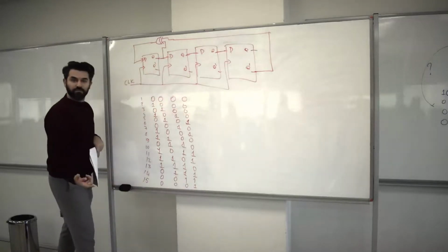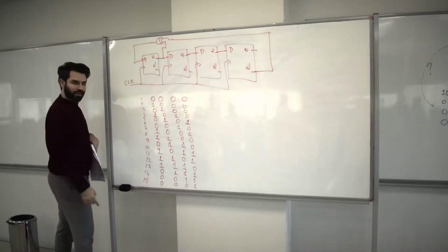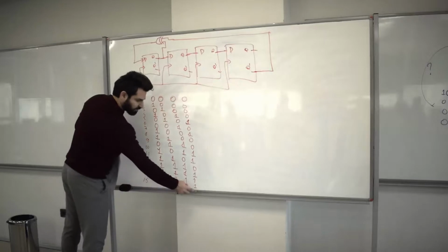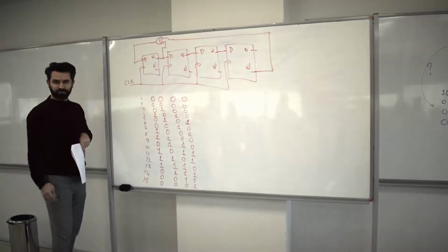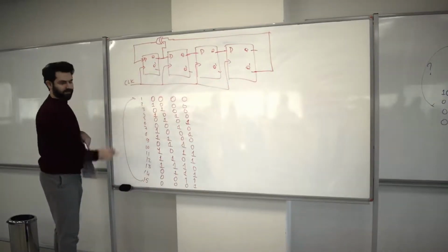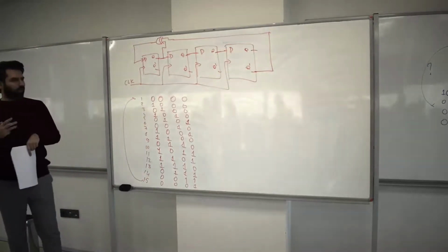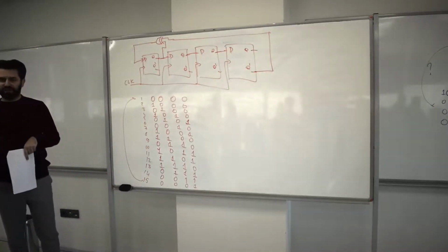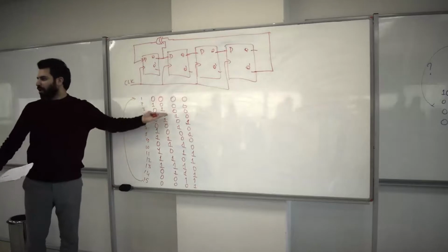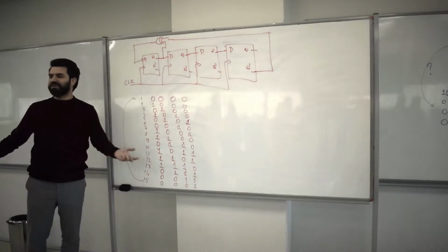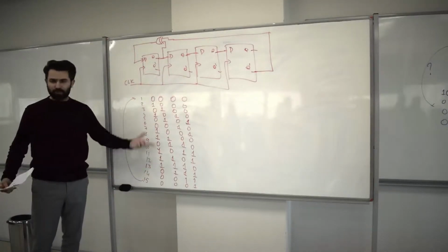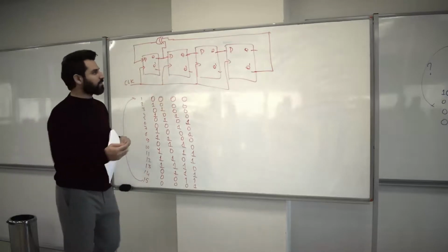This becomes 0. This is 0. XOR them. 0, 0, 0, 0. That's the first one. Okay? Now we go back. Did you understand why I'm calling this maximum length sequence generator? Because it generated all the possible binary sequences that you can make using 4 bits. Okay? That's why people call it.